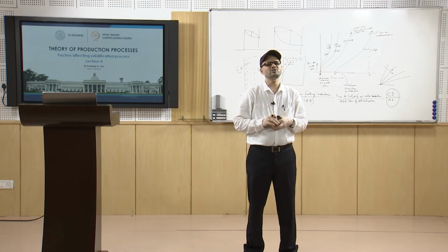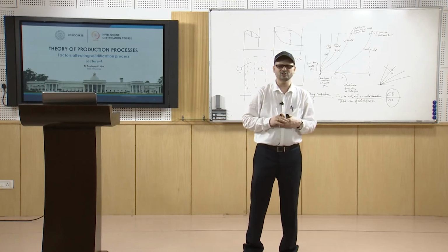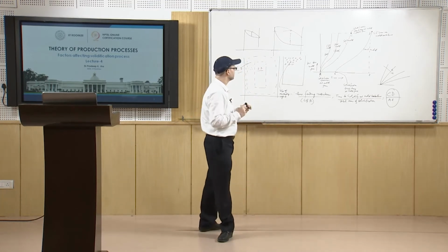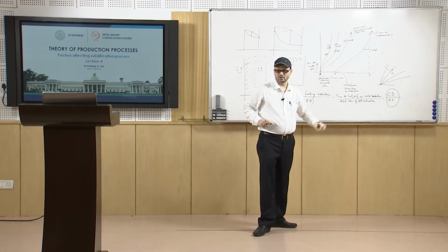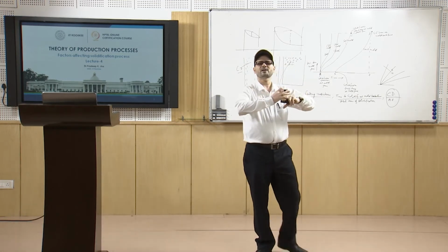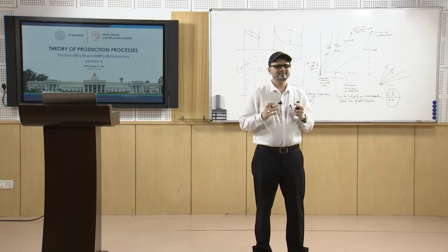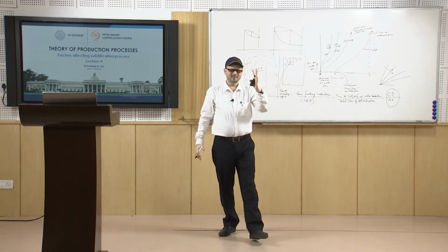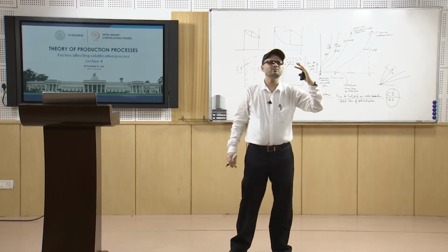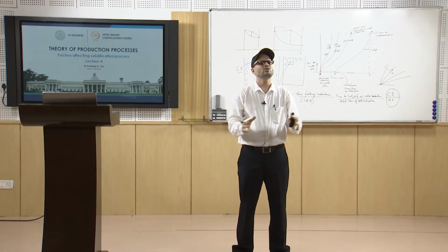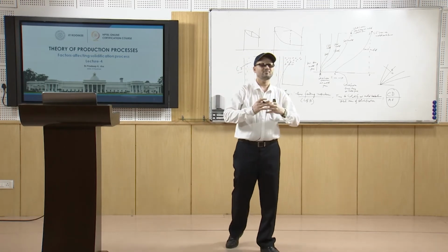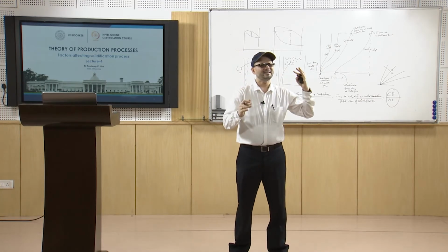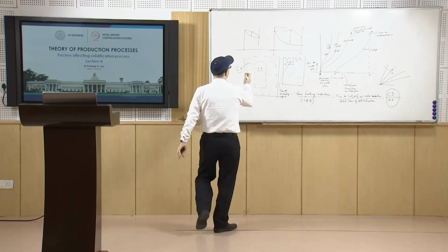Similarly, it is proportional to the freezing range. If the freezing range is more, the equiaxed grain proportion will be more, because as we discussed, when the freezing range is more, the center will take more time to solidify, and the temperature gradient line becomes such that random nucleation is possible because of the thermal conditions. So, when the freezing range is more, the columnar portion will be less.